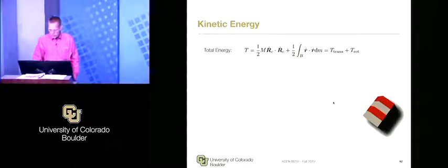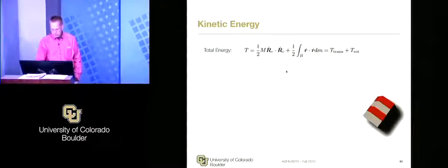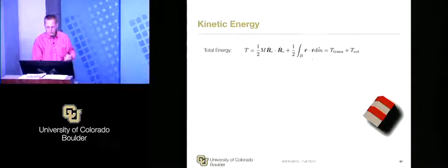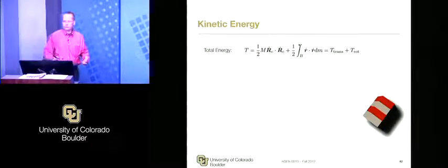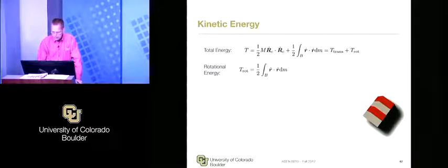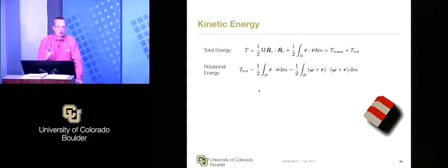The power equation, this was the general form that we had earlier, where this was the rotational energy, which could be due to deformation, but also due to rotation. Now that it's rigid, the second part is only going to be due to rotation. There's no deformation. It's rigid. So what happens then is the translation of rotational energy, same thing as before, focusing only on the rotational side. The translational energy, that's really your orbit energy equation again, basically. We're not using that part. But the rotational energy here, R dot, as Joe said, is omega crossed R, dotted with itself. If you see something like this, you just know there's some magic trick formula that makes your life easier.